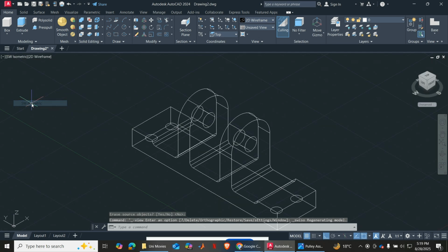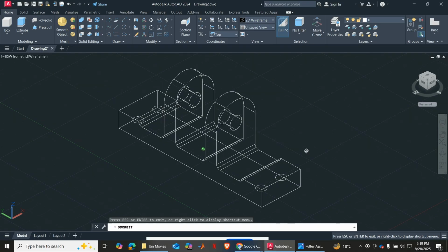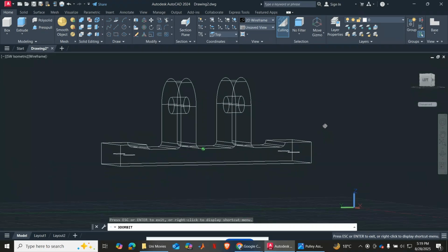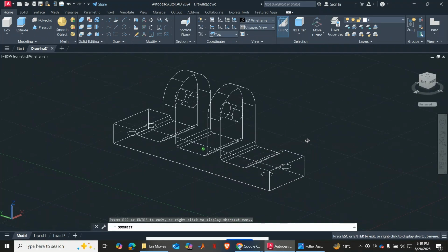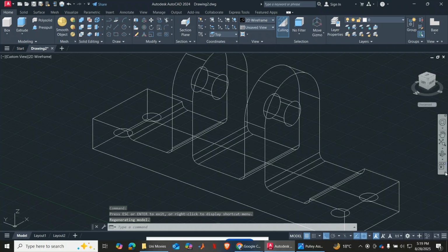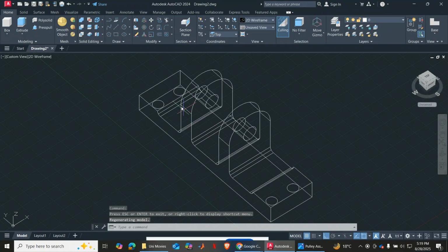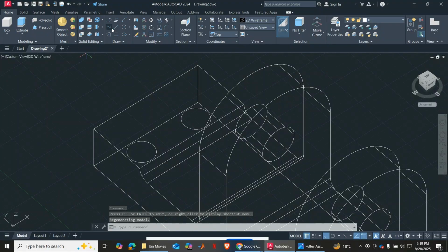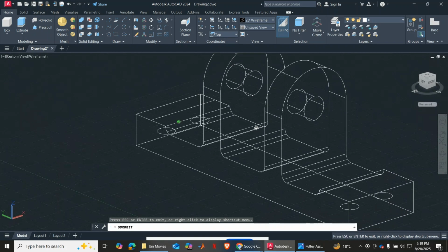So southwest isometric, where are they? They are there at the bottom, at the very bottom of this. Oh, they are at the very center of this object. Okay, so what should I do? I can move them to the top and extrude them down. So what I can do is I can draw a line from here to there. Okay. After that, I can say move.